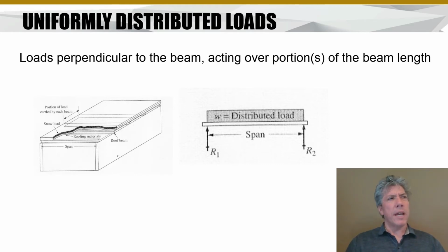Now if I remember right, technically the piano and couch and those things would all be considered dead load, because they don't move, they're static loads. But the live load is, say I had a party and had a whole lot of people in that middle room, well then that would be a live load. They'd be moving around and could even possibly be modeled as a distributed load if there were enough people.